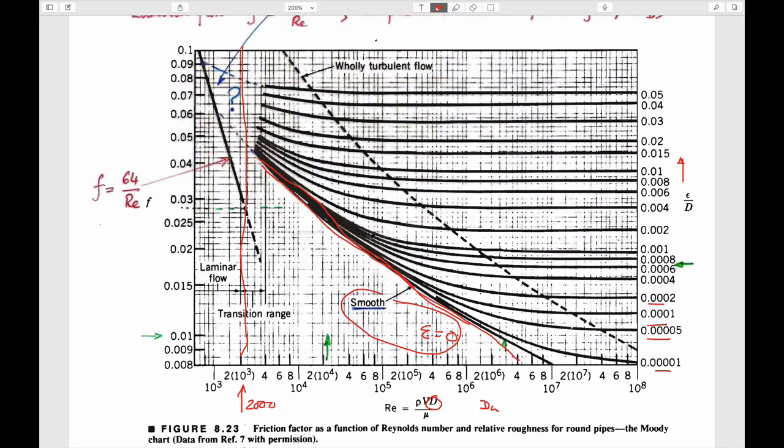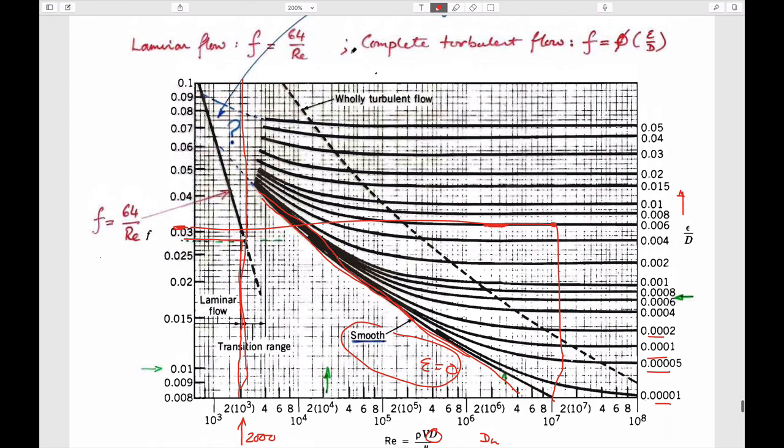And so the useful thing is that if it's fully turbulent flow, you only have a single friction factor to deal with, right? Because at a given high Reynolds number, for a given roughness of the pipe, you have a single number, and this doesn't change. So it makes the solution much easier. If you're in this laminar regime, when you go up here, the friction factor is always a function of the Reynolds number. And so in a different regime, it changes with Reynolds number. If you're trying to solve it as a function of Reynolds number, you need to keep this in the equation. If it's turbulent flow, then the friction factor is always the same.